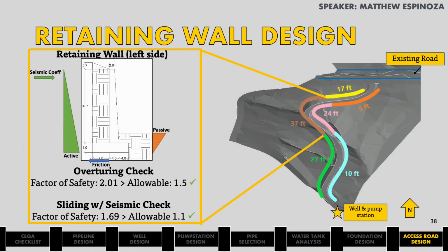The retaining wall was required to reduce soil excavation and provide a roadway from the pump house to the main roadway. Following Caltrans standards, the retaining wall will consider horizontal seismic coefficient, peak ground acceleration, passive and active pressure, soil density, and angle of friction.